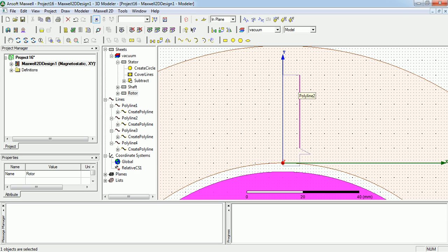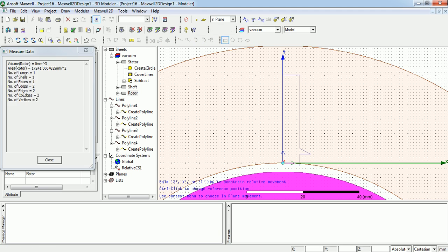So in this case, I need to draw a particular arc over here. Since I need to draw an arc, I need 3 points, the radius and the 2 endpoints. For that to happen, if, say, 3 mm is the radius of the arc, I have to draw a square with a side of 3 mm. So that is the procedure. So I'm going to draw a square right now.